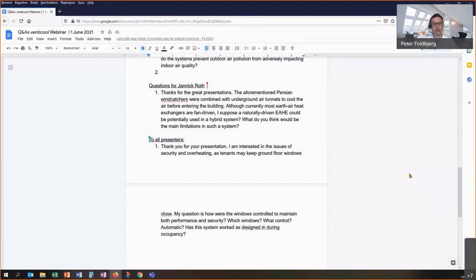But it's definitely clear that opening big facade windows raises an issue of compromising security or privacy for some people. For example, in the house in Brussels, we used small top-located openings in the larger window, so it was sectionized, and these windows do not compromise the feeling of safety or burglary in the same way. So that's how we controlled it.